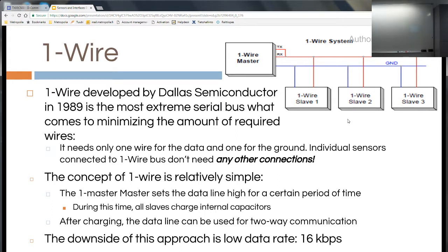Okay, so this master basically just initiates the transactions, and there's a well-defined, predefined protocol with quite strict speed constraints. So the clock rate should be exactly right, not just around there, that kind of thing. But anyways, you can put a lot of sensors on that OneWire bus, and the master just goes first.